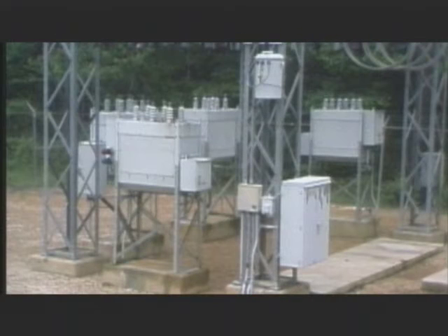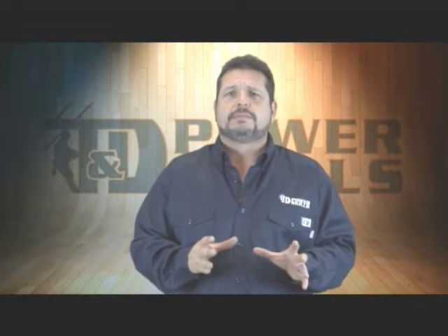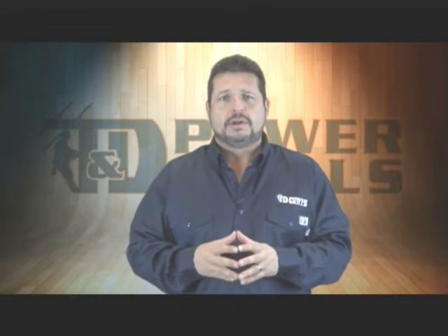But there are some similar-looking devices in many substations that perform a very different function. This is a special kind of oil-filled switch called a recloser. In many substations, reclosers are part of the station's equipment for circuit protection. If there's a lightning strike on a distribution line or a fallen line, the recloser will open, and after a short interval, it'll attempt to reclose the circuit. If the condition is still present, the switch opens again. Many reclosers can be set up to attempt to close the circuit a certain number of times. Then, if the problem doesn't solve itself, the recloser stays in the open position, protecting equipment in the distribution system